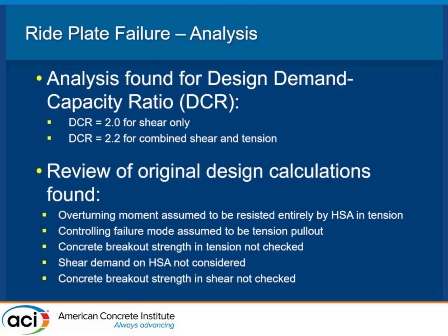Imagine if it's just running along and providing a downward force, there's just a moment, perhaps, and maybe you've got compression on one and tension coming up. But as soon as you try to stop, you're producing a shear force, and shear wasn't checked at all. We call these design capacity ratios when we go back and take a look at it.